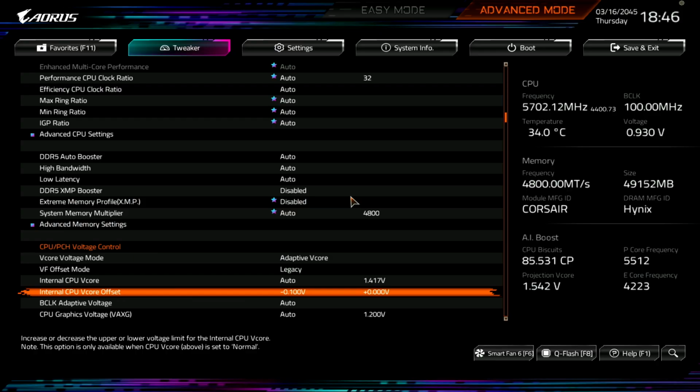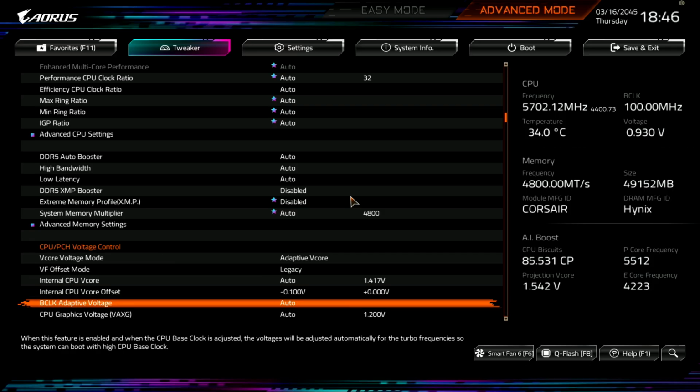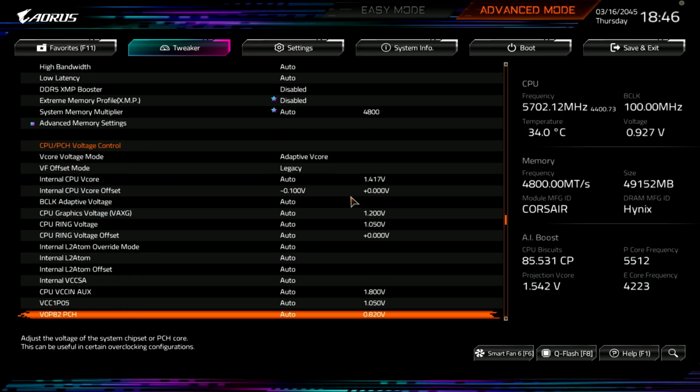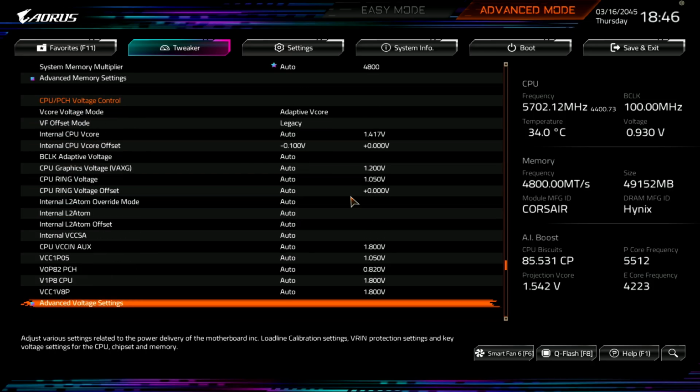As far as I know, I think Gigabyte's Renesas boards are all 1.1 milliohms. The ON Semiconductor ones might be 0.9, which might be why Gigabyte is setting all of their boards to 0.9. Having some of your boards slightly too low is better than having some slightly too high. You don't want boards being too high. Being too low is probably fine. Being too high is definitely a problem.